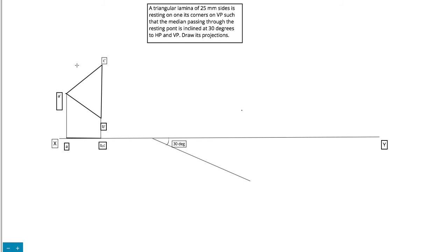Now we have to take this top view length in our compass, this one, and we have to draw it over here. So we can take this TVL in the compass. Starting from this center point, we can cut an arc over here. I think it should cut somewhere here, like this. Now we can name these points. So this will be A1 and this will be B1, C1. We can darken this a bit so that it shows up as different from the construction line.